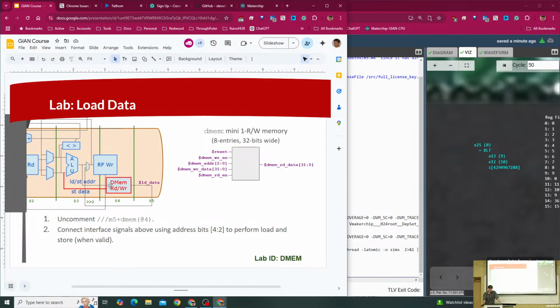So yes, the memory returns the load data a cycle later, but it's going to be associated with the stage that's one ahead, right? In part, your question depends on how the memory was created, but it was created to kind of fit in this pipeline. So the DMEM read data is associated, corresponding to the inputs in terms of their stage.